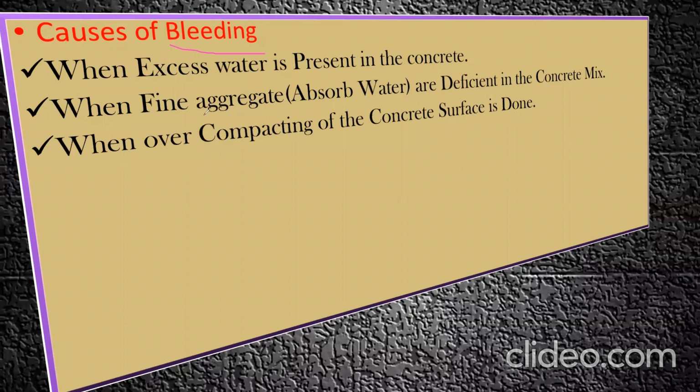Why is that so? Because fine aggregate is sand, and what it will do is absorb the water. Let us say you're putting more water, sand has that ability to absorb the water. But if the sand itself is less, then there is no one to absorb the water.